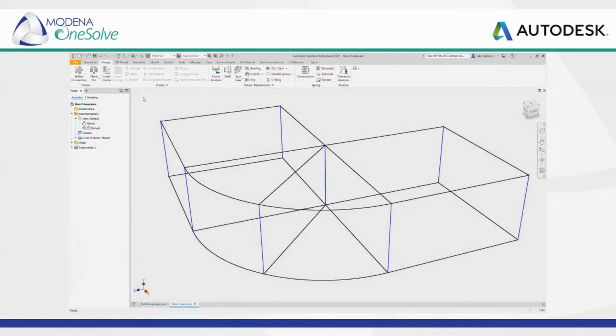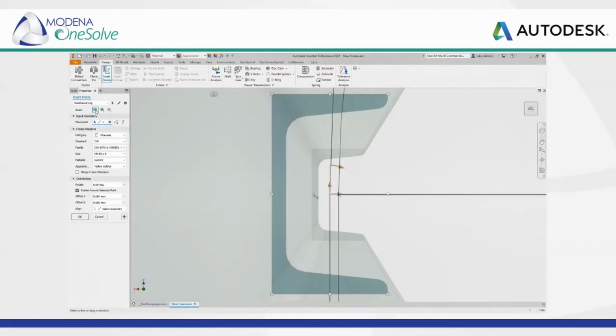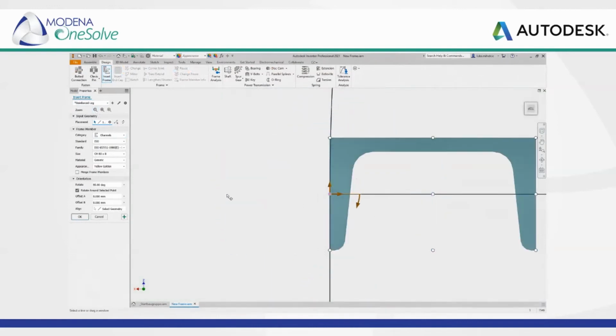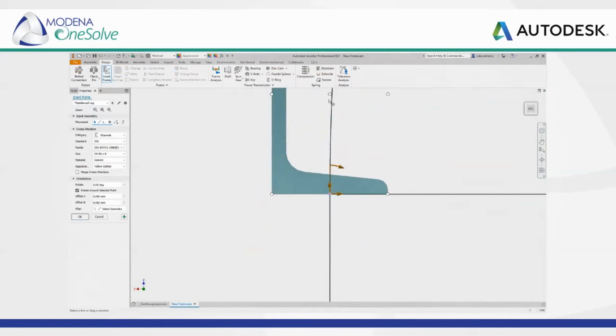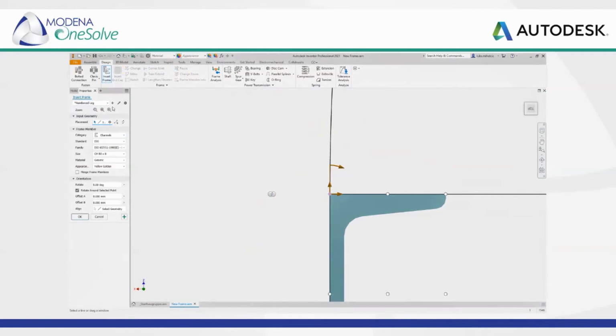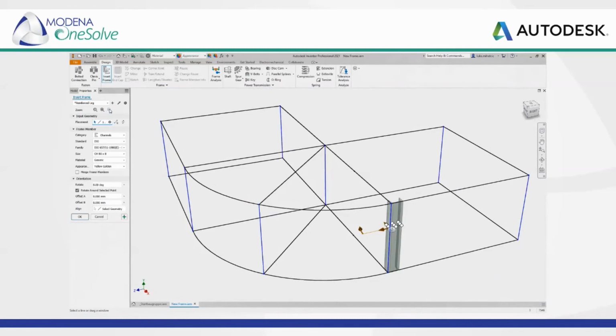When creating frames, a new category filter allows you to narrow down your selection. And preset configurations now help you to save your most frequently used frame settings for use again later. Geometry can now be filtered from within the property panel, and a new preview glyph helps you to orient your frame as you select your skeleton geometry. Once you've selected your geometry, new zoom tools help you to orient your frame by adjusting your view to look directly at the frame section or an isometric view of the frame member you're placing, before zooming back to see the entire design.